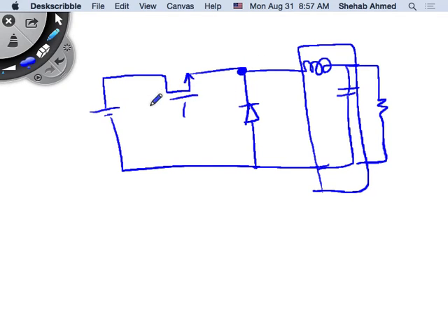is it something that I would like to see both devices on, or is it happening just because of the reverse recovery? During only the reverse recovery, both devices are on, but that's something in the transitional stage. So forget about that. From a power conversion perspective, either the diode is on, or either the MOSFET is on, and if the MOSFET is on, it is taking this 5 volts and putting it here across my load, right? And if the MOSFET is off, the inductor current is flowing through this diode.